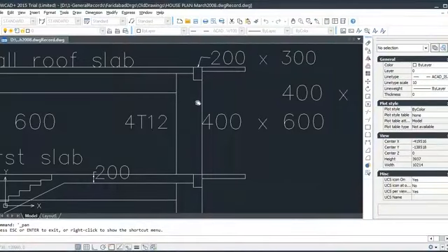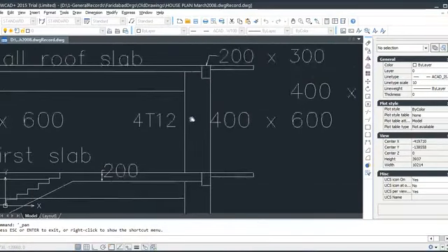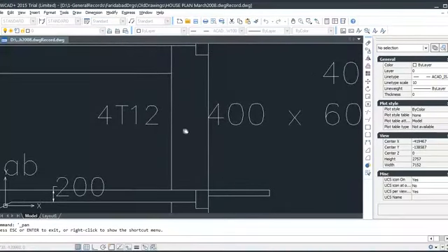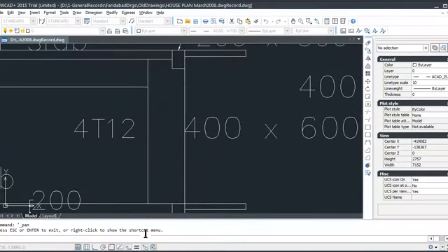This is the practical way. Some people say we cast 1 meter of column first or 2 meters, but that is not preferable. It's better to cast the full column if you have the complete technology for how to pour it.